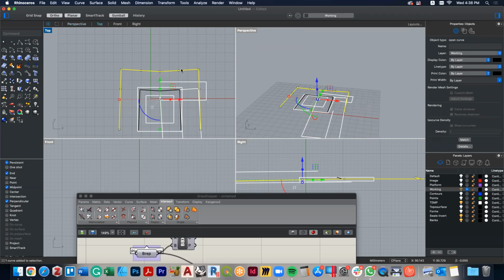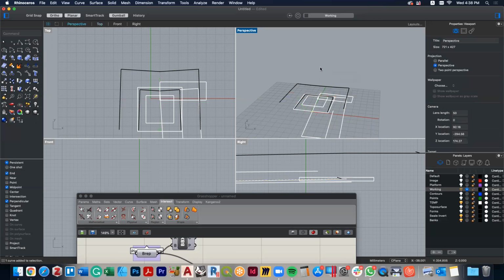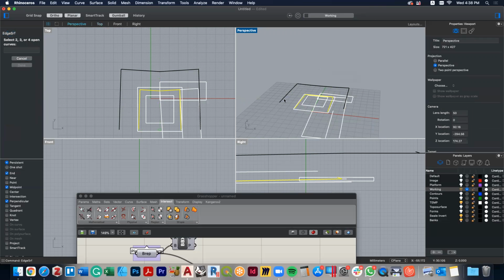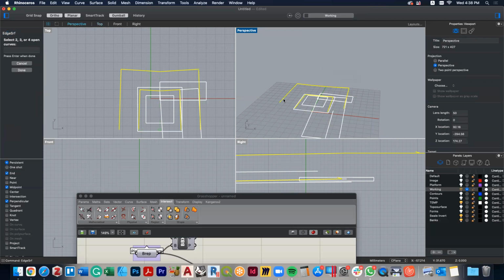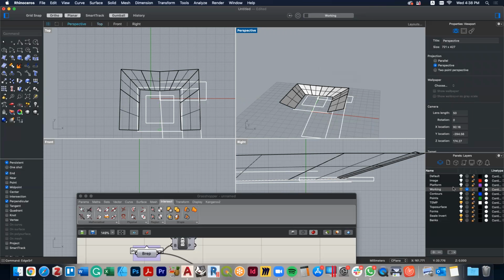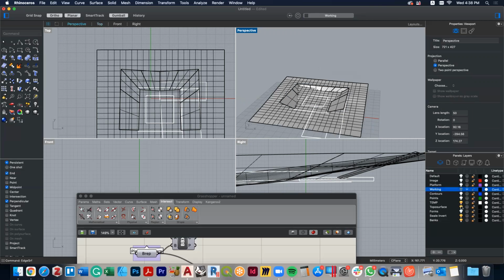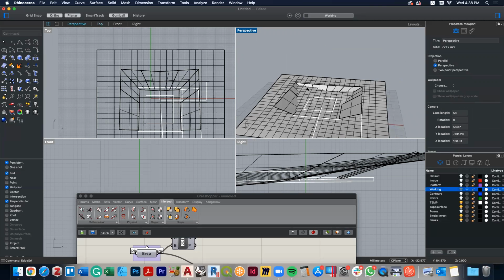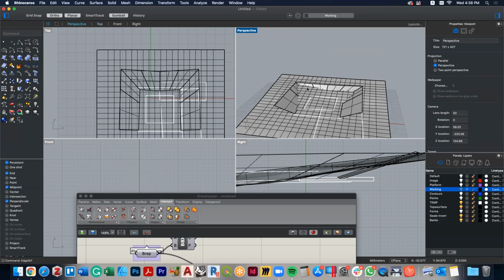And now I move it up to 7, because it was 21, 3 7s are 21. So I go to 7, move it up. Again, I do an edge surf, and I go from there to there, enter. There's my surface. Let's turn on that topo surface again. Are we out? We're out. Okay, finally, we're out.